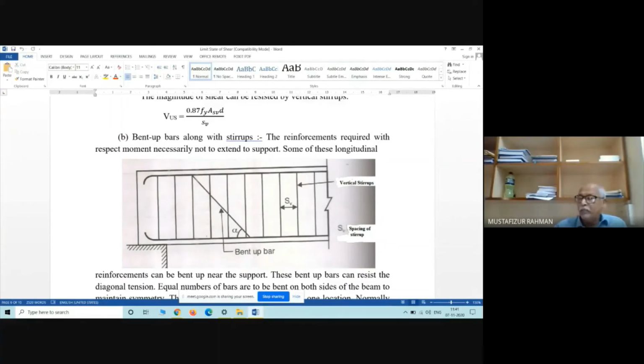So to keep it in position, we have to bind all the rods, both at the bottom surface as well as the top surface. So for that also, we will require the stirrups. Number one, to keep the main reinforcement in its specified position, we require stirrups. Number two, concrete.